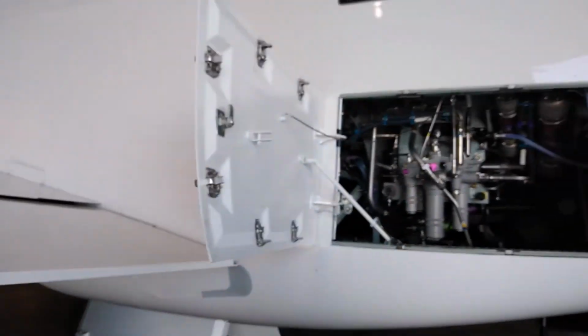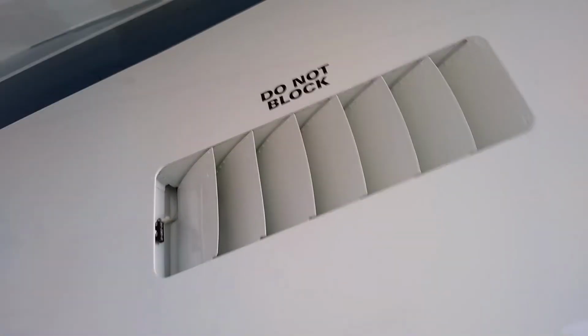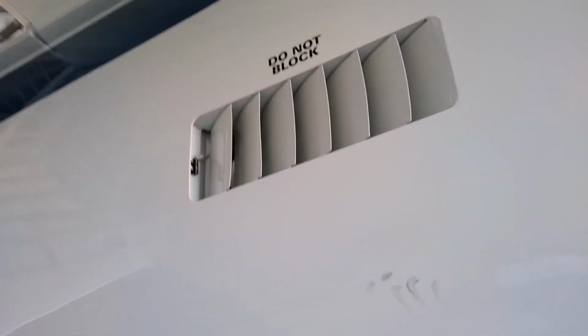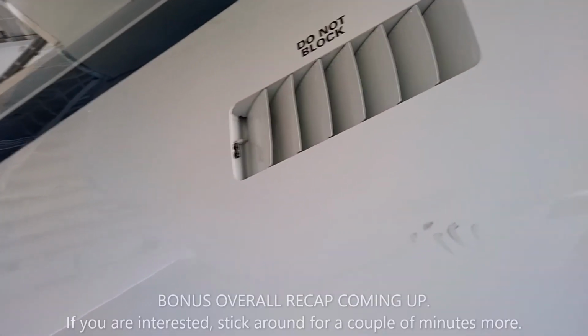Now we're in the back of the airplane. Again, all that air is coming through all these fairing areas. All that gets vented. And it ultimately exits through here. This is one of those outlets on the side of the fuselage. Now we're in the back of the airplane underneath the left engine. And that is the ultimate outlet of cabin air pressure. And again, you have one of these on both sides of the fuselage.